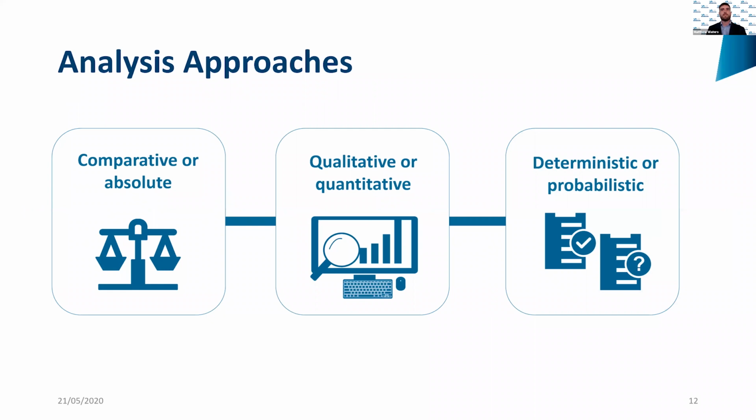There's obviously a few different analysis approaches that can be used to analyse performance solutions. We've talked about comparative or absolute from satisfying a performance solution or documenting a performance solution. A comparative approach is just simply one where we're comparing against deemed to satisfy. An absolute is where we're doing an evaluation directly against the performance requirements and we're not doing a comparison with DTS. So quite often, if performance requirements are qualitative or it's difficult to quantify, the comparison with DTS option will be selected because it's a little bit simpler to benchmark it.